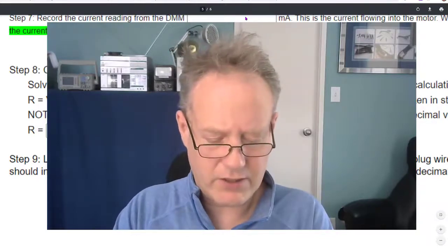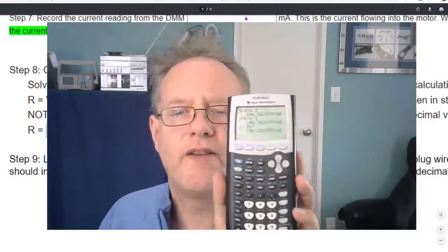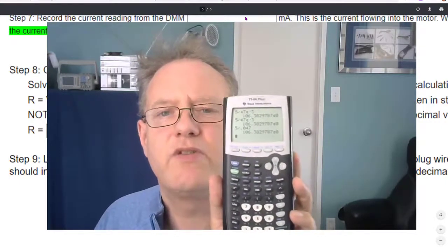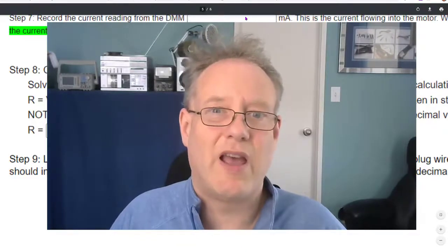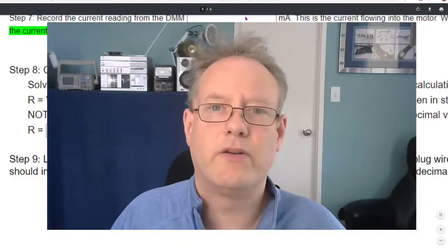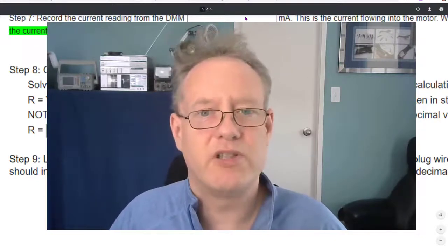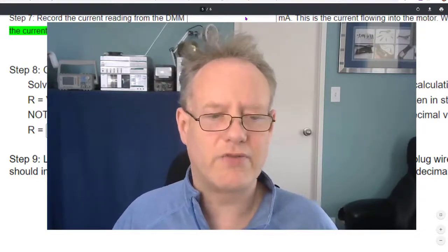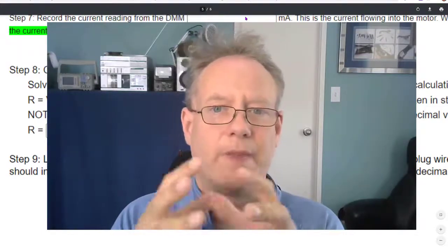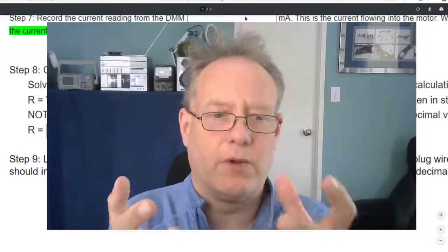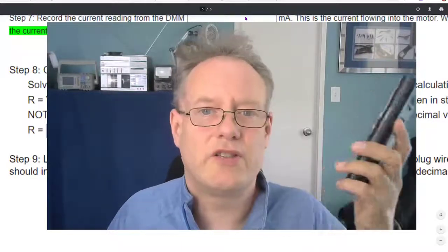5 divided by 0.47, and you see, it gives you the same number. 5 divided by 0.7 gives you the same number, because 47 milliamps is 0.07 amps. No, I just lied to you. 47 milliamps is 0.047 amps. So however it is, if you want to calculate the resistance, you have to physically put in a decimal in this calculation, or you have to use engineering notation.